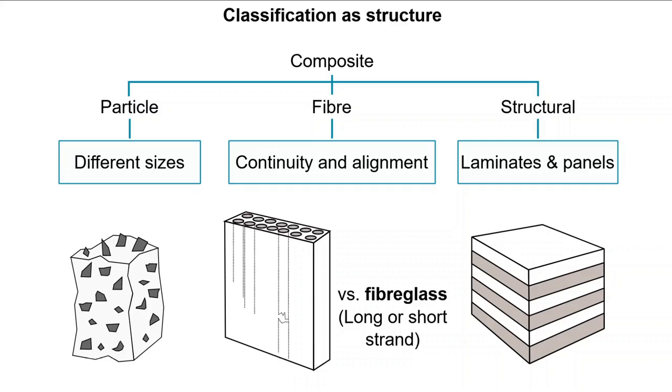As an example, body filler for automotive purposes is sold under two variants, short strand or long strand. The former is used for filling small bodywork defects, whilst the latter is used for structure or a foundation for short strand. Longer strands add strength, but cannot be finished smooth in the same way that short strand can be.